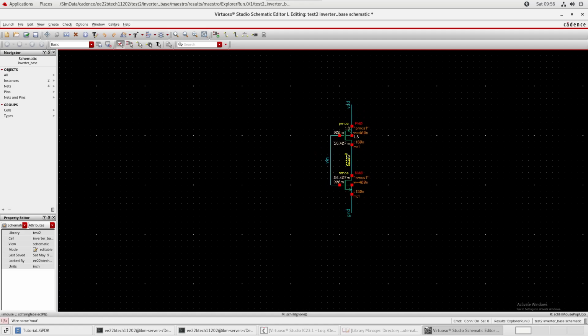You have some GND, you have some V out, V in, VDD. You want to use this and integrate it with some other things. Maybe you want to make an inverter chain. How do you do that? You need to make a symbol for it or something. Even like op amps and all this, they have all these symbols so that you can integrate them on a bigger level, right? For that to happen, you need to have ports.